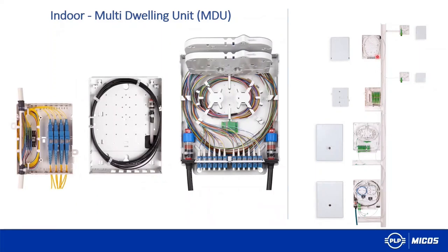Yeah, and here you can see actually how it looks inside the building. So those are independent floors. First you have a basement where you connect the outdoor cable or duct, micro duct, with indoor cable. Then you have floors where you can have a different type of boxes, and you do the distribution from each floor to the different apartments. I don't know, most common here in Europe, I would say, is 4 apartments on one floor, but it can be 8, it can be 12, it can be even more, it can be only 2. So it depends what box you use.